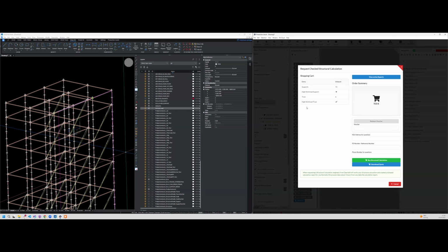Yes, you can do both. Basically, it's always the center lines of the beams that need to be added. So there is some overhead for preparing the blocks. We are currently in the process of doing this together with Bert, so that all the blocks in the SCAD library automatically work. But then you can calculate any type of beam structure and do the calculation for this.